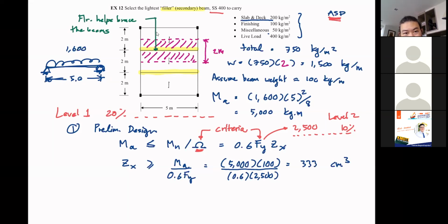If you really wish to include the weight of the truss members in your analysis and design, you now have to run the truss as a frame, because the weight of your member is a uniform load. There is no such thing as a perfect truss in the world. You always have bending moment and axial force in a truss. But because the weight is so small, we can neglect the bending moment in the truss, but it's there. That means it depends, right?